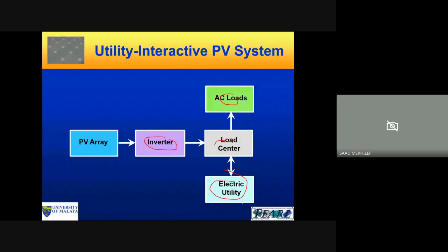It means if we have extra power, we can sell to the grid. If we need power, we can buy from the grid. Storage can be added, but we need to do a techno-economic analysis of the system to see if it is feasible or not. Whether to have storage depends on the price of the feed-in tariff and other costs of the system.